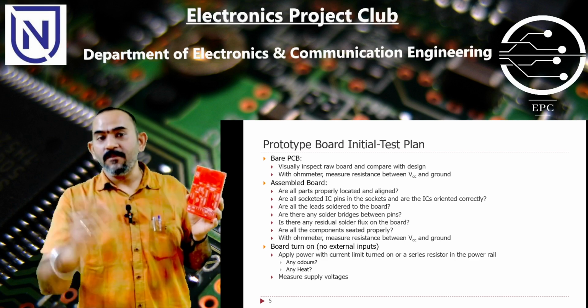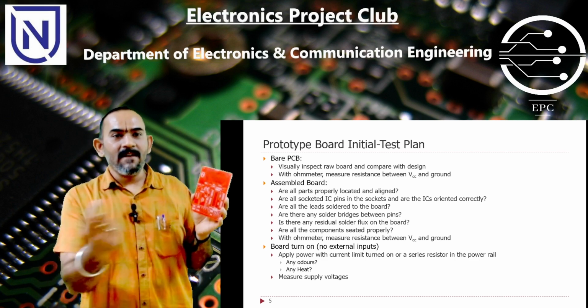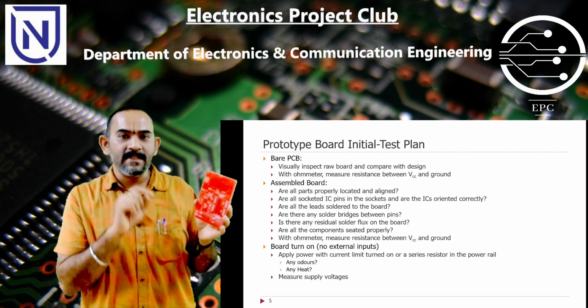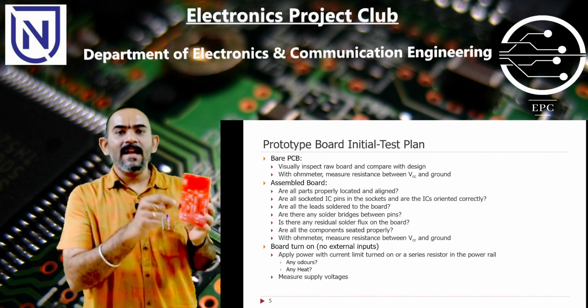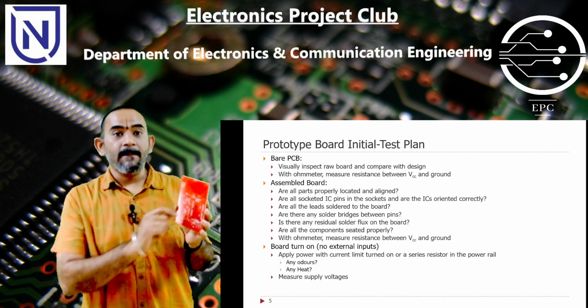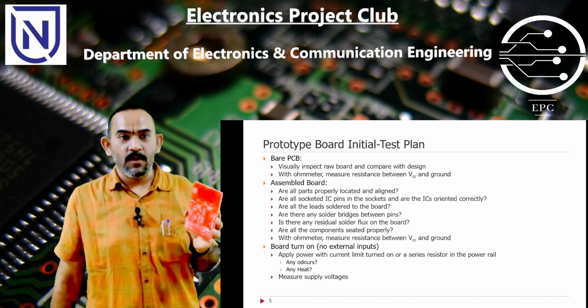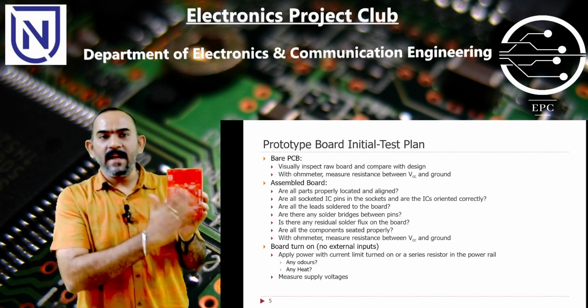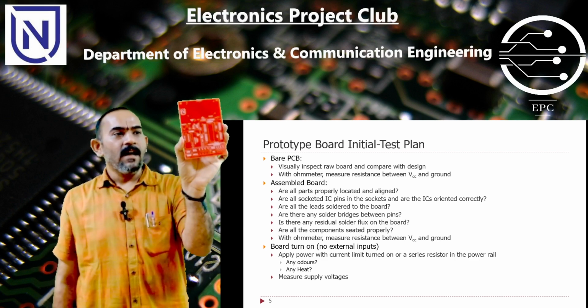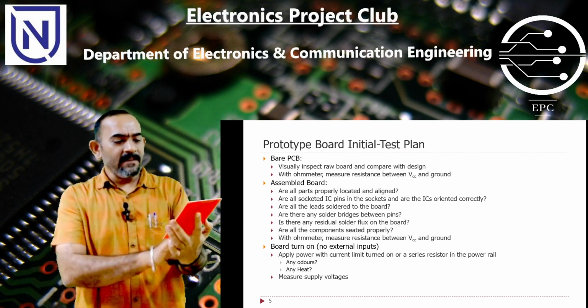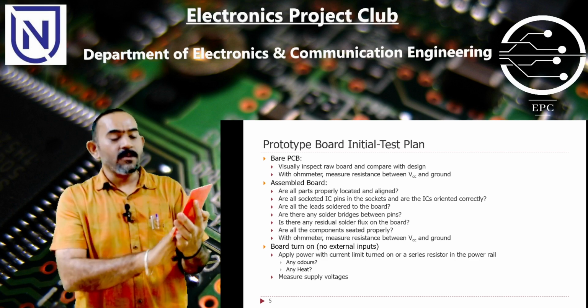For example, if you have seen an Arduino board, they will not have a complete silk screen, only some components will have it, because the board size itself is small. They can't fit all the part numbers, reference designators, and so on. But it is generally a good idea to have a silk screen. So first, look at the board and see that there are no errors or mistakes on this.